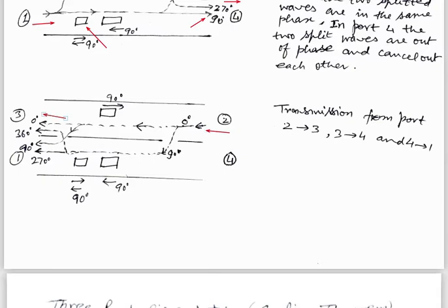And in the second waveguide, the first wave, after splitting from the first 3 dB coupler, will have a 90-degree phase difference due to the non-reciprocal phase shifter ferrite slab, and 90 degrees due to the resistive pad. So the total phase difference will be 270 degrees in this wave.